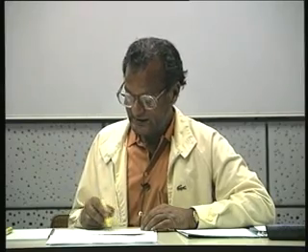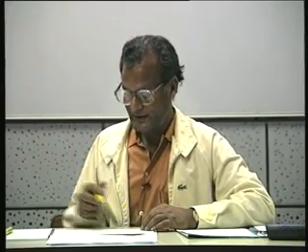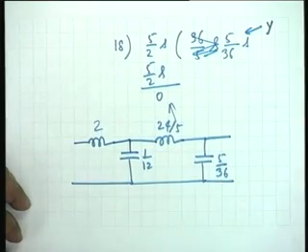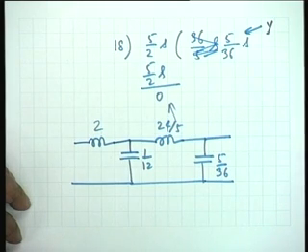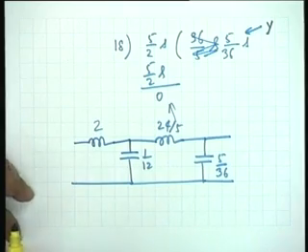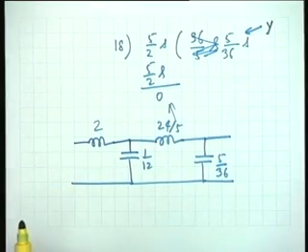It has to be that way, there is no other way. There are exactly 4 elements, and the last element is a capacitor, because the function had a pole at the origin. Don't ask why you have an open circuit.